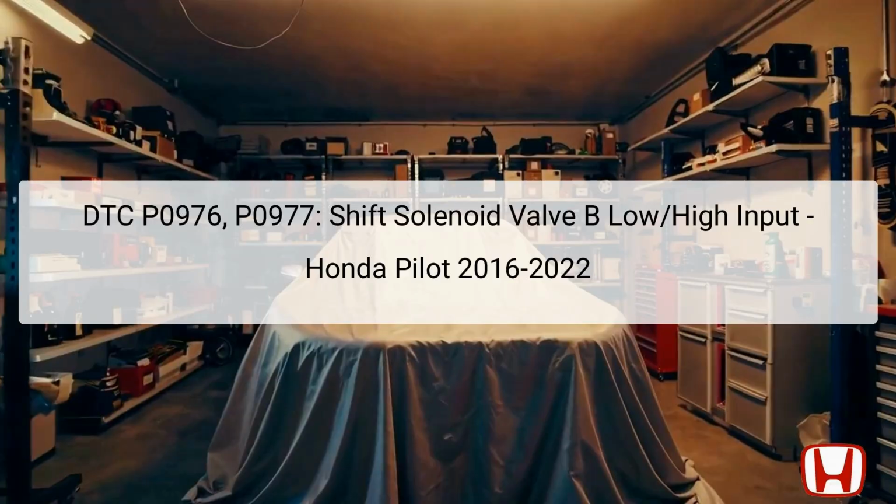Today, we will be discussing the Diagnostic Trouble Codes, or DTC, P0976 and P0977 that pertain to the Shift Solenoid Valve B for the Honda Pilot produced between 2016 and 2022. These codes indicate issues with the electrical circuits affecting the solenoid, which is crucial for the vehicle's automatic transmission system. Specifically, DTC P0976 signifies a low input signal from Shift Solenoid B, while DTC P0977 indicates a high input signal.